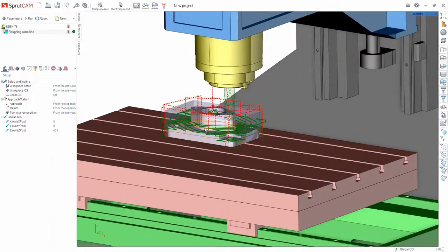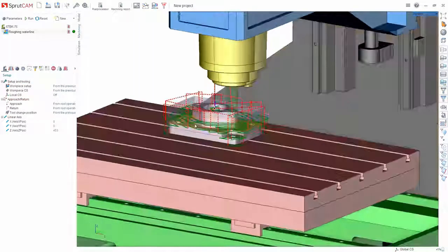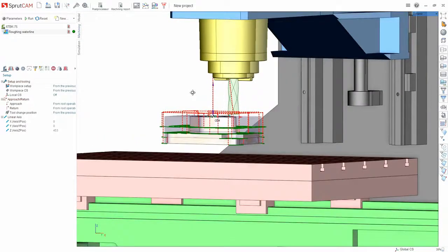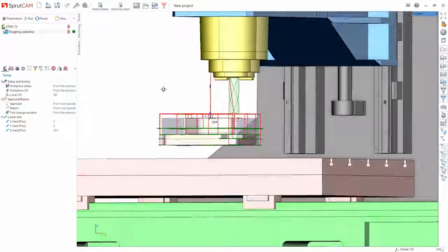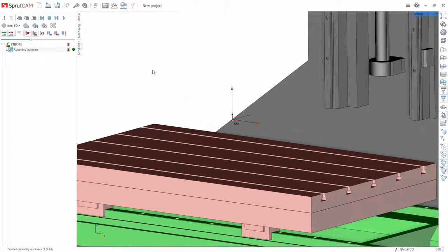We see the path and something might not suit us. For example, a step by Z. It's quite big here. We can fix it all later. So we looked at the finished path, determined things we are not satisfied with, and begin to adjust the created operation. Select the tool, set the modes, correct the removal along Z-axis, correct the approach along the arc if necessary. We always see the result in simulation and how the material will be removed.